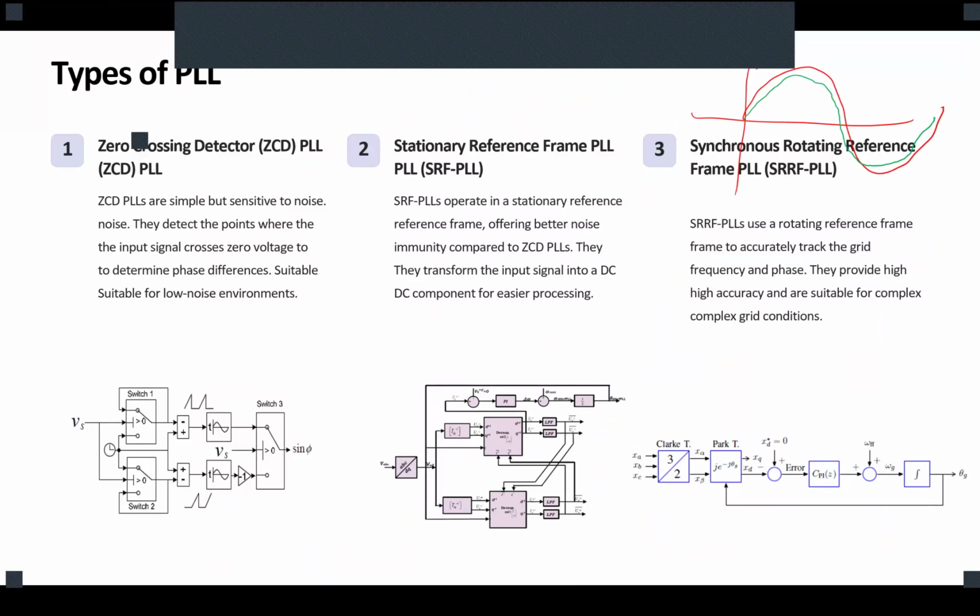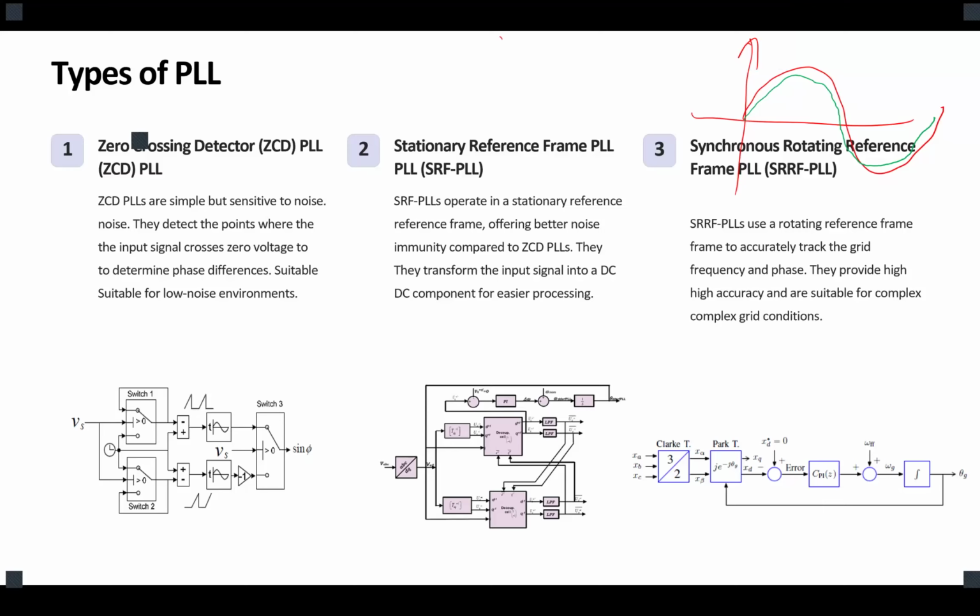At each time, when the system wants to decide how much active power it should drain from the system, it looks at the theta that it sees between the inverter and the grid connection. The system doesn't know we have a slight frequency change. It assumes our inverter works perfectly and is synchronized with the system, but in reality it's not.